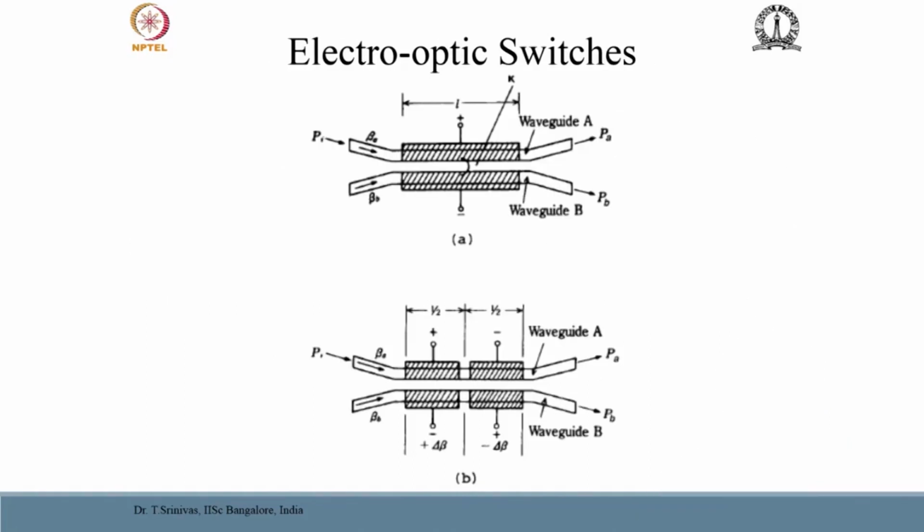So, this is another example of electro-optic switches that we have already seen. There are a lot of configurations that we can think of. Typically I would like to highlight the second portion, where there is a delta beta coupler. You can choose the voltages across these couplers to change the properties and tune according to the requirement, and you can also compensate for the fabrication tolerances and the minor electrical voltage variations and get a very stable modulated output by such a configuration.